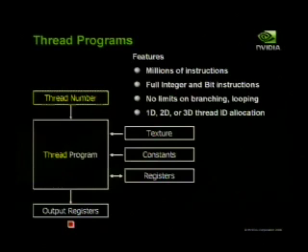Along the way, they actually improved the fragment program because they realized that having only floating point instructions is a little constraining. So the big features are these programs could be statically 1 million instructions long. Effectively, every function that I want to run over a set of data can be up to a few million instructions. There's full bit and integer support. So we basically have x86 or CPU parity instruction sets. The only thing missing, I think, is branch indirect. So we can't do function pointers, but pretty close.